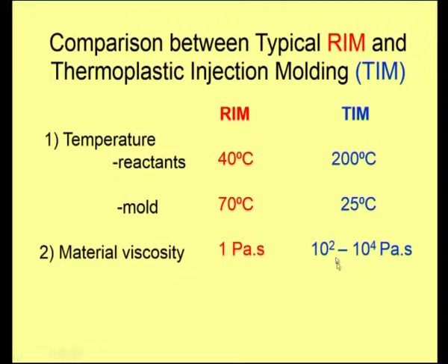So, it has its own issues related to rheology, that is, if the viscosity is very high, then the polymeric melt flow would not be uniform, or in other words one has to increase the speed of the screw, and the screw efficiency has to be maintained at a very high value.